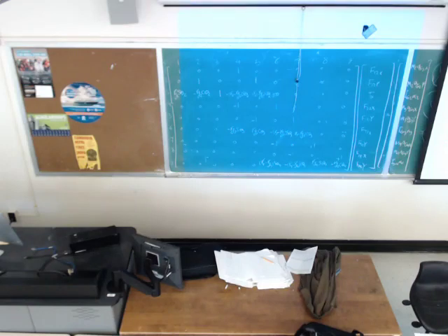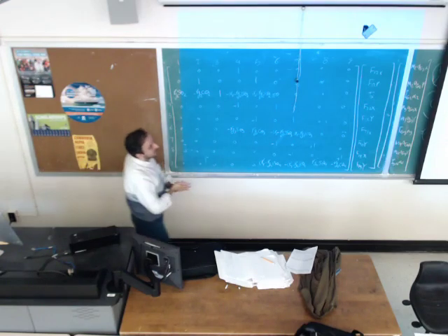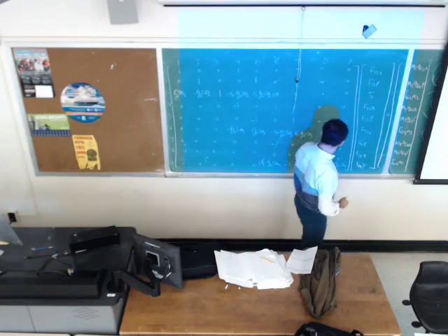So you are given, or you have calculated, the terms that you can see on the coefficient matrix. This is a coefficient matrix, and this is a constant matrix. So you have everything that you need by performing the kinematics analysis. So you have acceleration of center of gravity in X, acceleration of center of gravity in Y, and for link 4 and link 3. You have mass moment of inertia, you already know alpha 2, alpha 3, and alpha 4. Then you can do the force analysis and find this way.